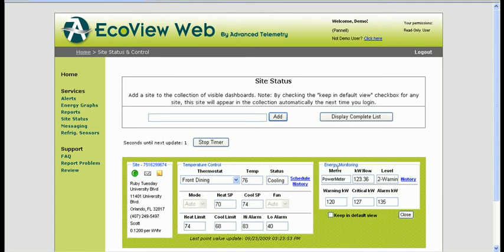Next, we have our energy monitoring box. This is in conjunction with our power meter that is constantly reading the kilowatt usage of this particular site. Right now it is on level 1, good. We set these thresholds here, and we have a warning, a critical, and an alarm level. If this kilowatt usage ever reached above 135 kilowatts, it would send us an instantaneous energy alarm.